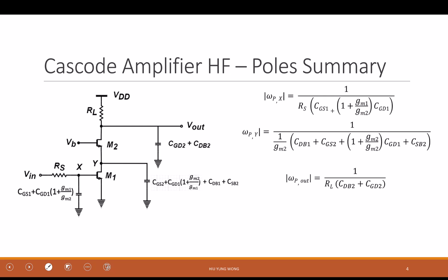So it is a Cascode, and why? Because the input is here, output is here, and the first thing you think is, oh, that might be common source. No, but then the output is not at the drain, right? Because it goes through the source, which is constantly biased at the gate of another transistor, and then you go to the output, right? You should recognize this device right away, right? So we talked about the Cascode circuit last time.